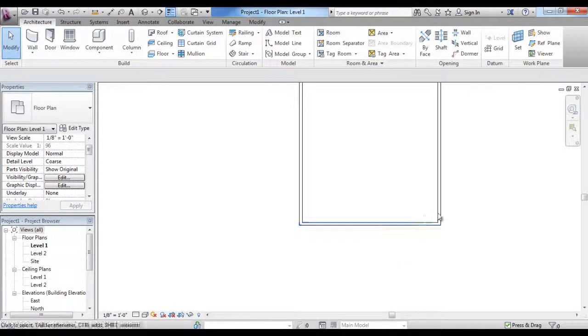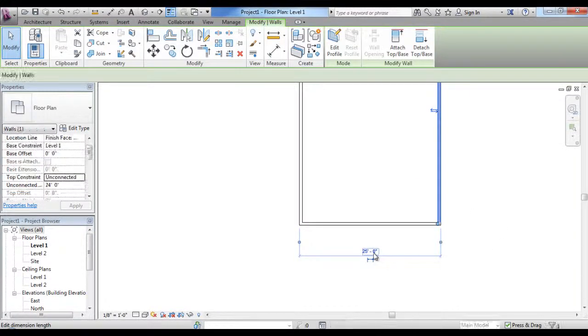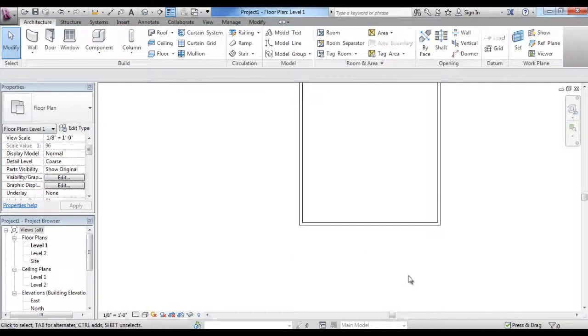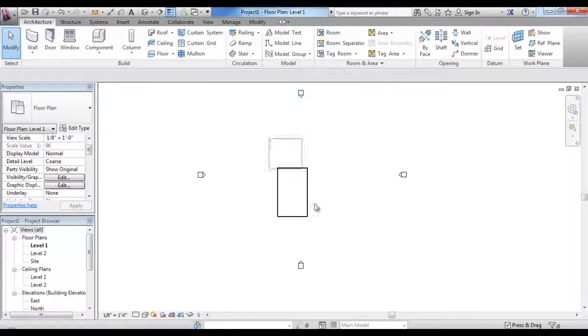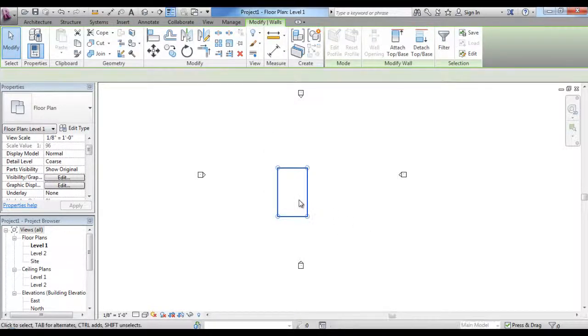Okay, and just to be clear, when you click on this, you've got to first select this, get your witness lines in place, and then click here. And then you can change that measurement. Okay, and as we noted in lecture, Revit defaults to feet.